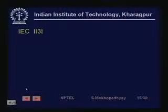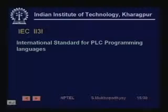Now, having said these things, this, in very brief, is a structured design approach to RLL programming. Now we must mention, since we are coming to the end of this programming part, that there are certain standards of programming languages which have come. For example, IEC 1131. IEC stands for the International Electrotechnical Commission, and 1131 is a number. So this is an international standard for PLC programming, and it classifies languages into two types.